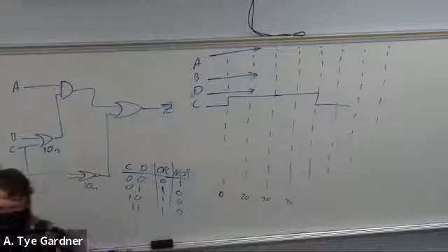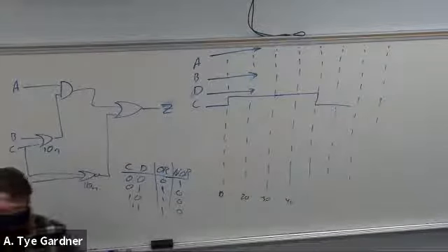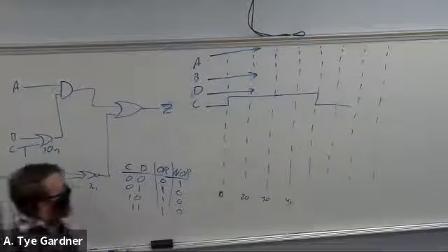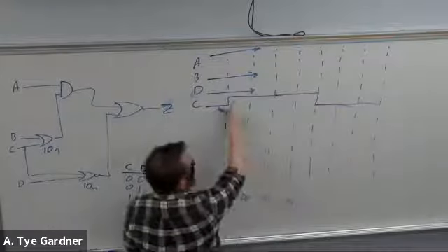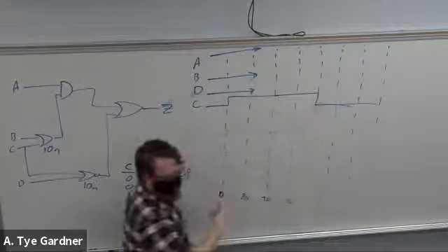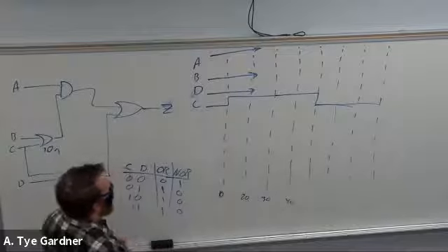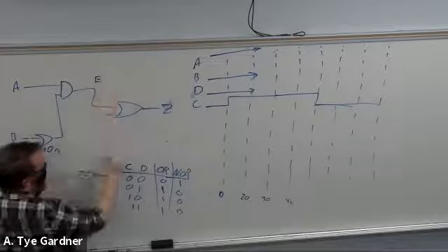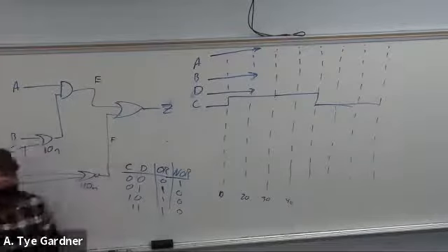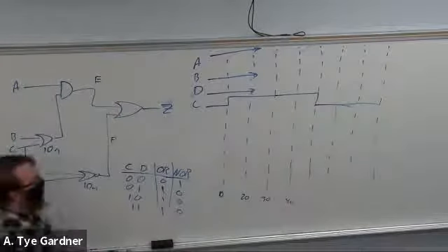Right, just so that there's enough time for it to resolve the full delay path. And then we'll stay here. And now I have my 0 to 1 transition and my 1 to 0 transition. And we could just start by finding if there's a glitch. Start by labeling the nodes, E and F, and finding out what they do.